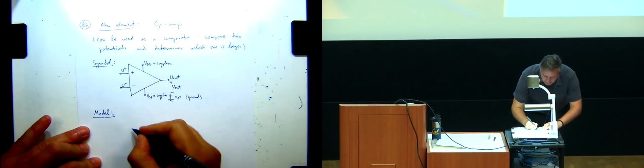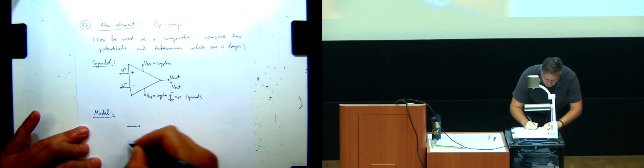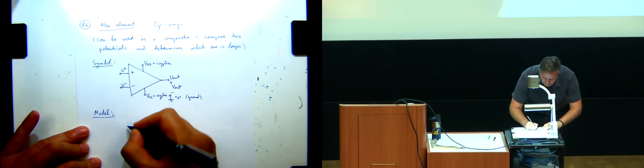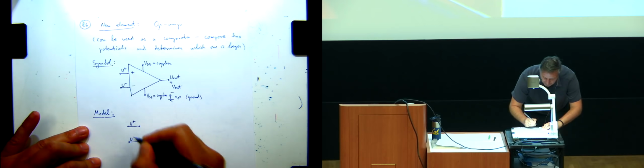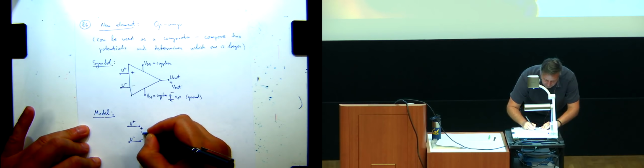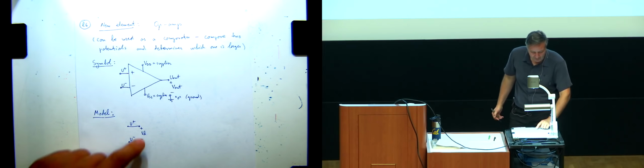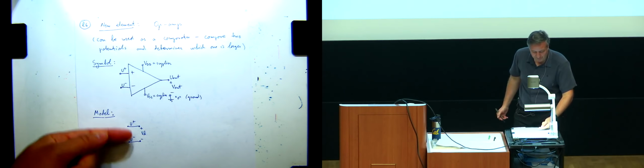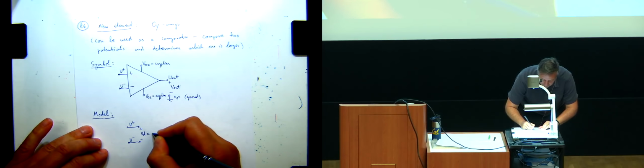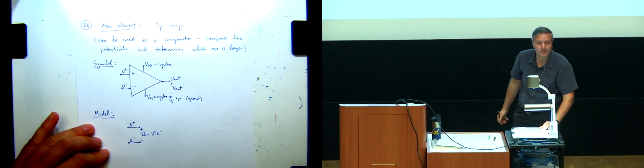Here is how it works. These two terminals, U plus and U minus, basically give you this control voltage, VD. VD is just the difference of these two potentials, U plus minus U minus, because of this plus and minus.